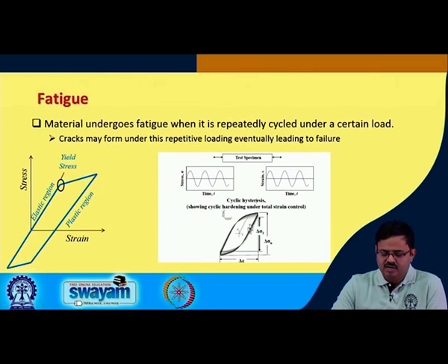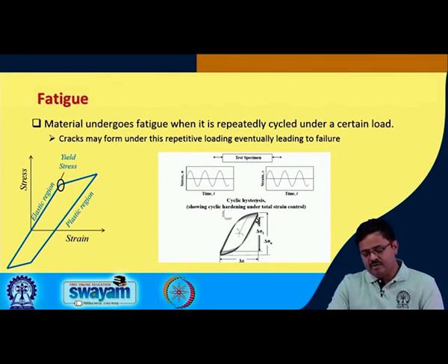But later on what is happening is, here I started, I went like this, I came down. In the next cycle, as I increase the number of cycles, you can see for the given strain the stress goes up, and also for a given stress the strain goes up. So, this is fatigue, right.